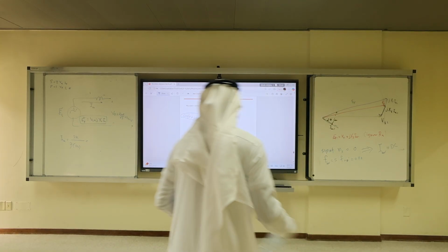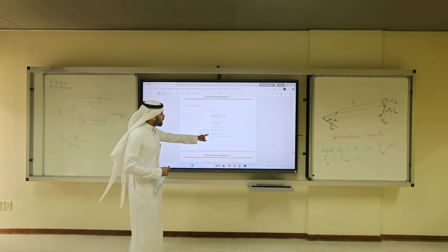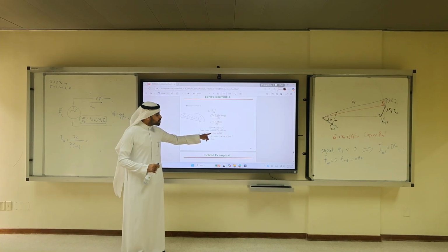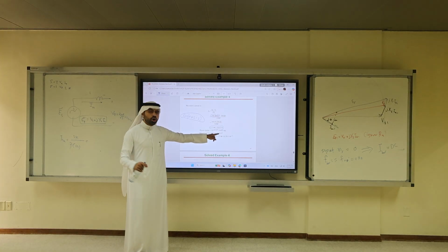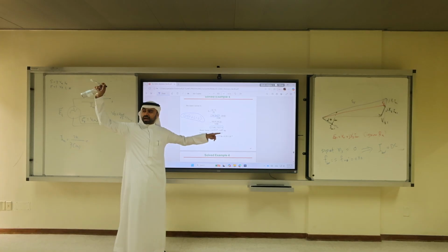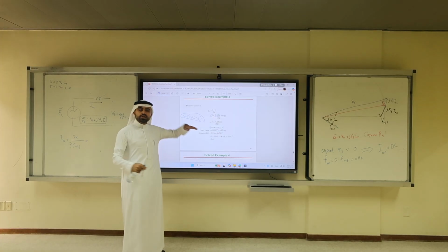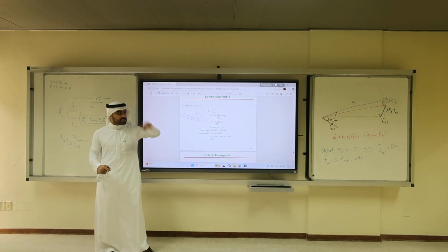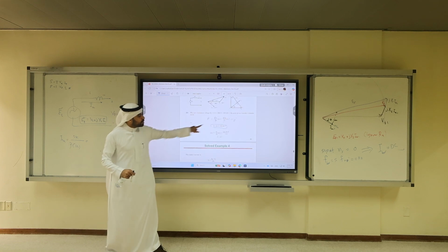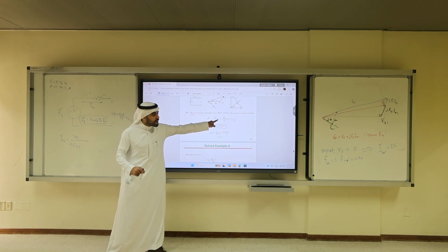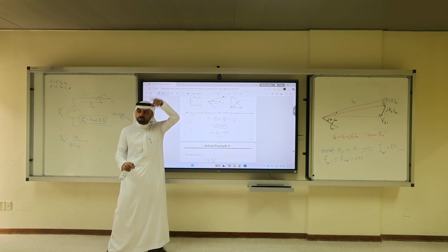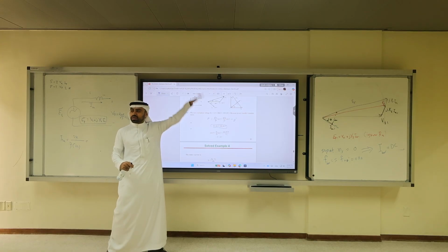So this is how to solve this part, and then you can calculate the reactive power, which is 3 Vt IA sine, or you can use the big equation that has cosine delta. There is one equation before that is similar to this equation, but has Vt EF over Xs cosine delta minus Vt square over Xs. There's one equation that I wrote before.